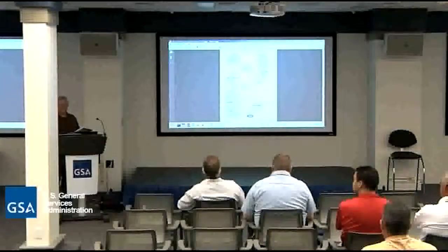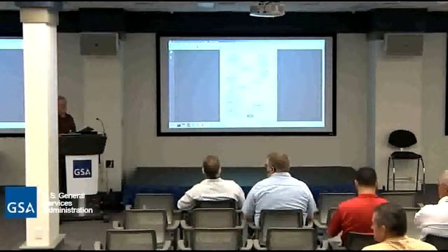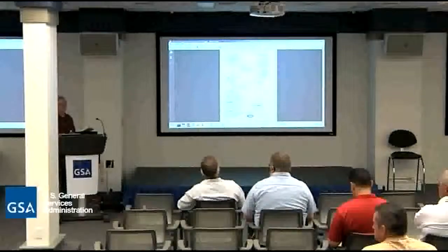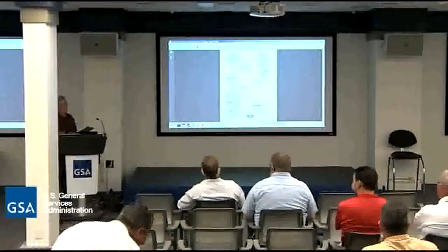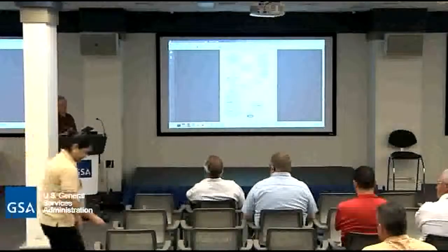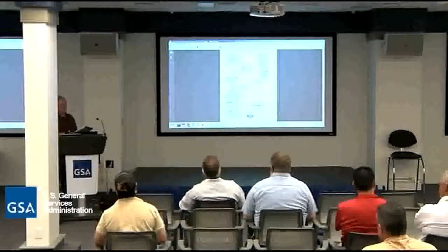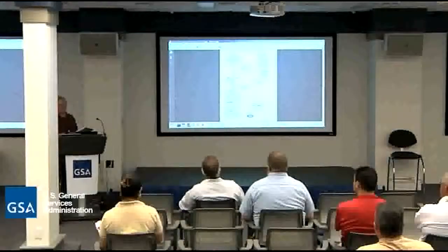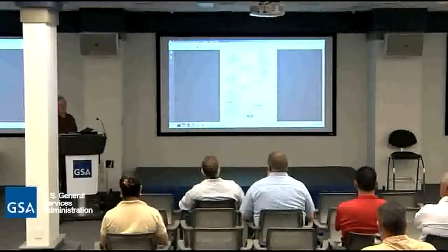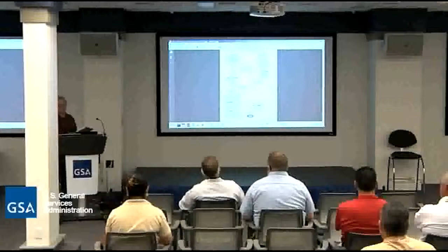The only exception that we've got on this is that if you're dealing with wallboard, even though the sampling may indicate that the wallboard is not ACM, we have a general policy of going in and, unless there's strong information that's brand new and we know it, sampling anyway. The reason being is that on the DFC there has been 60 years of remodeling, and that particular 4x8 sheet of drywall may have been replaced recently, or it may be original. So we always go through and resample on drywall.